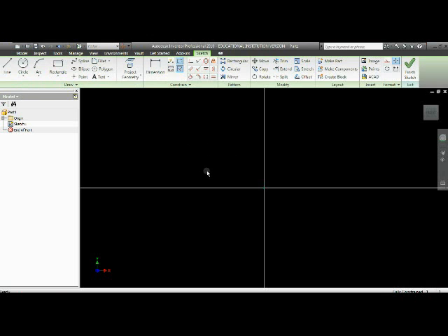Again, it's the environment that will allow us to create three-dimensional parametric solid. Now, what do I mean by parametric solid? Well, what we're going to do here, and there's your graphics user interface. We're going to sketch a part two-dimensional. We're going to either extrude or revolve it, and we're going to make a three-dimensional parametric solid.